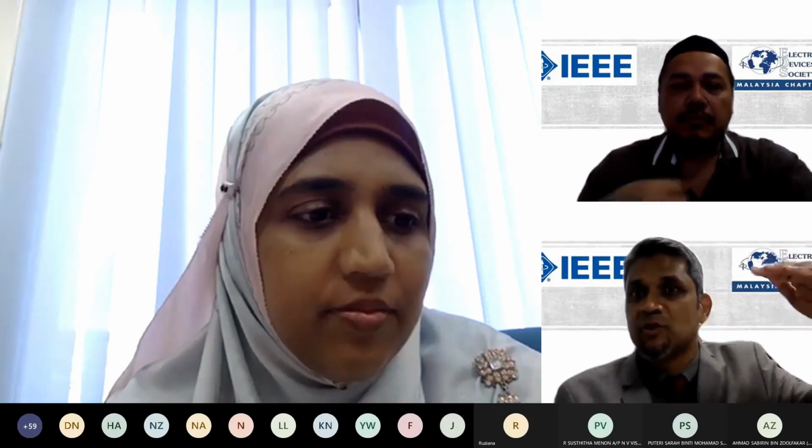Okay. Indium gallium nitride. Thank you so much for your appreciation. Indium gallium nitride is the other cell, like the gallium arsenide based solar cell. It's a multi-junction solar cell, one of the materials. Indium gallium nitride has a band gap that can absorb the high energetic photons. So you alone cannot work with indium gallium nitride only, because if you see the solar spectrum, the UV is coming very little. So that's why you have to tandem with others.